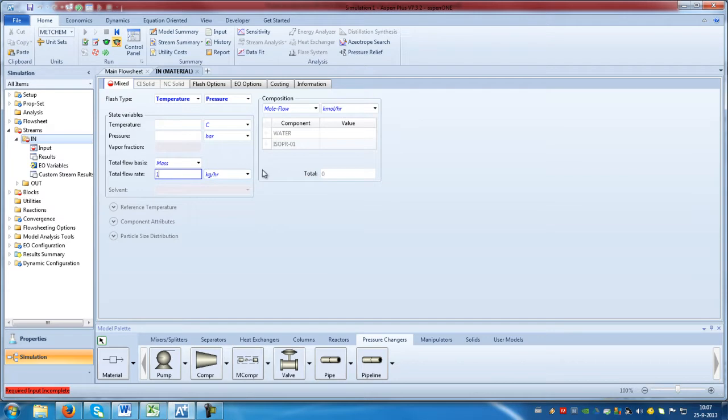In my case I will take a 10,000 kilograms per hour stream, and first I will do water, and for a pump it's important that there's only liquid, so a good estimate is to put your temperature in between the melting and boiling point. So in this case that's 50 degrees. Maybe for the isopropyl alcohol we will change it later, but we will see. Maybe it just works also at 50 degrees. So in the first case most of it water, only a bit isopropyl alcohol.